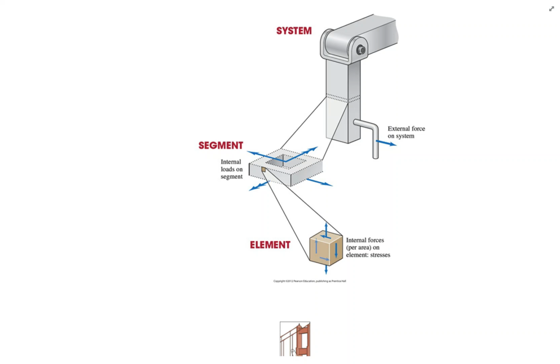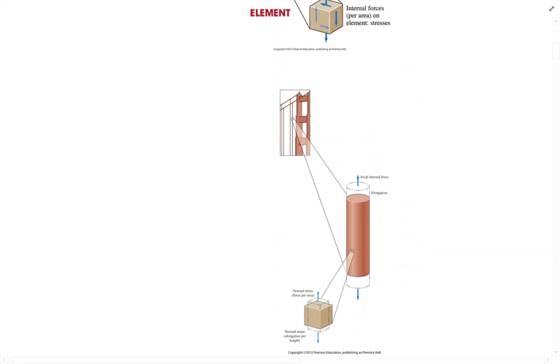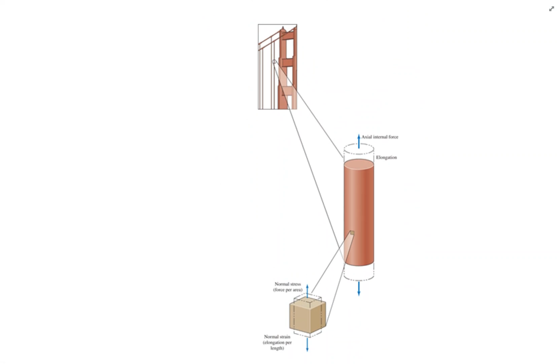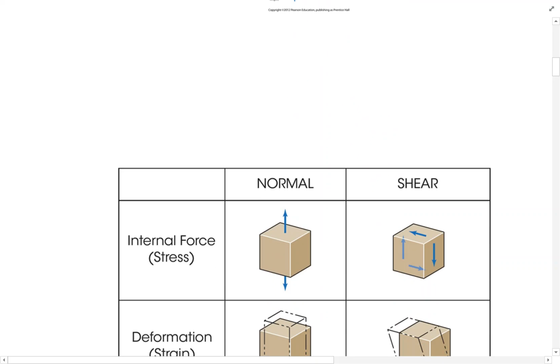And this plays into something we'll spend some time on, being finite element analysis, where you take a structure that you've modeled, impart loads onto it, all kinds of different loads, and then look at the result that you're going to get in terms of stress in the part, as well as strain. So it's a very useful tool. And you can use not only mechanical forces, but thermal effects as well. So again, just another example of that. This is another structure with a tensile force being applied to it, and how does that weigh into the element side.